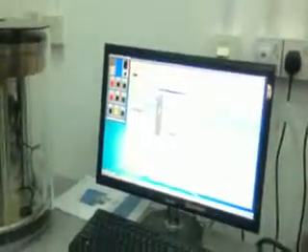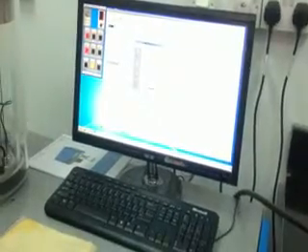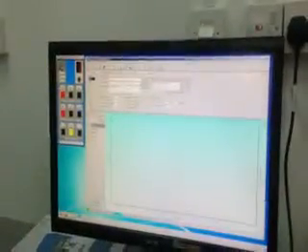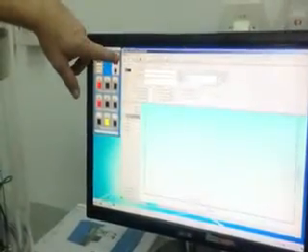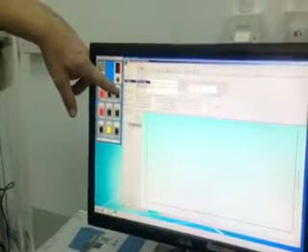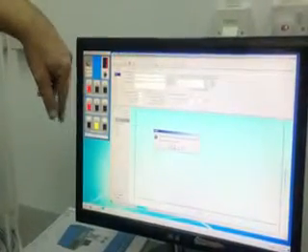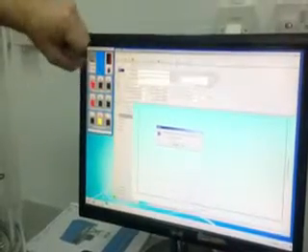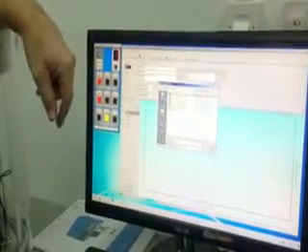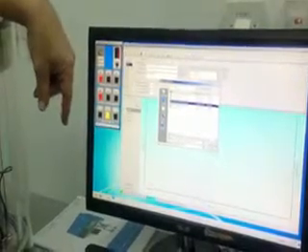Then you can modify. For example, I want to do the test between 40 and 60 degrees. How can I select the file here? This is for saving, so if we cancel and not save, because it is wrong, we go File, Template, Open Template File. We say we don't want to change anything at the moment, so we go No. If we call up this template, it'll load that template from the computer, and at the moment there is a green tick. That indicates that your settings on the screen are the same as what you have in your template.